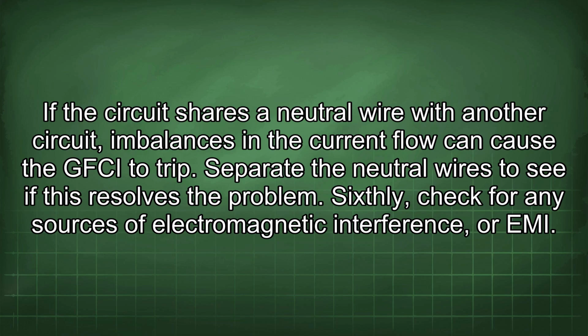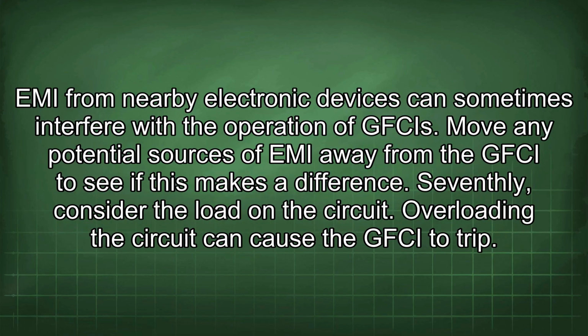Sixthly, check for any sources of electromagnetic interference, or EMI. EMI from nearby electronic devices can sometimes interfere with the operation of GFCIs. Move any potential sources of EMI away from the GFCI to see if this makes a difference.